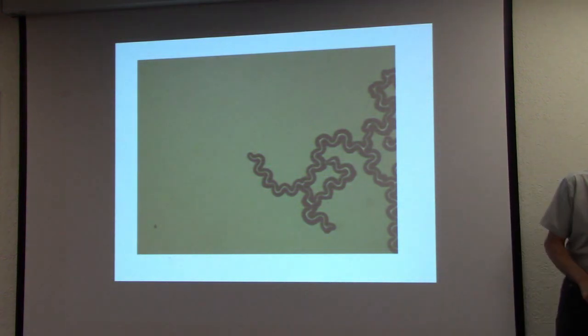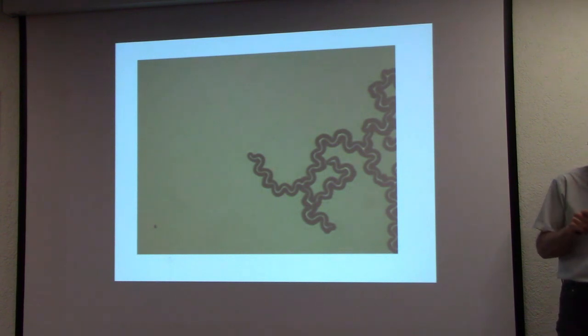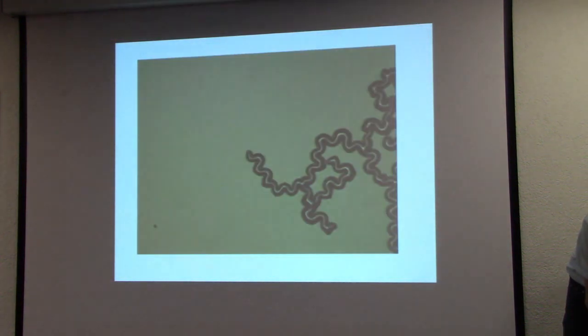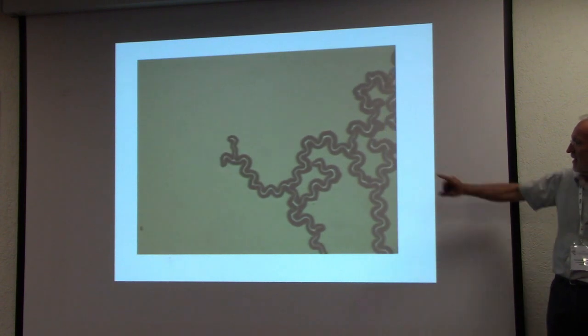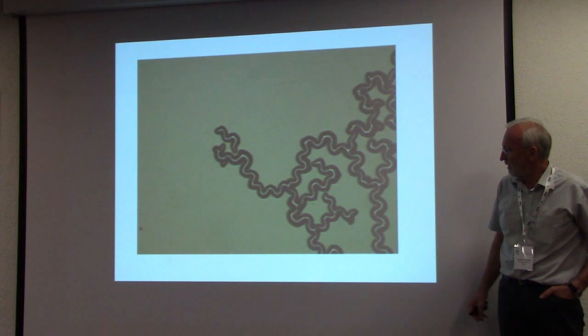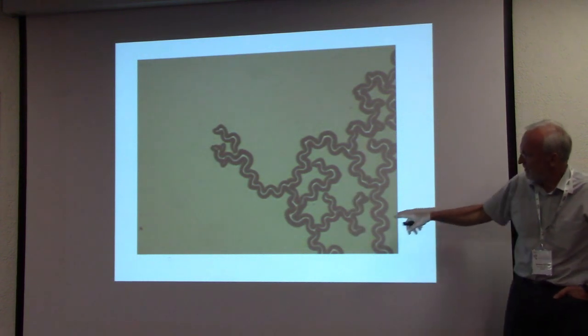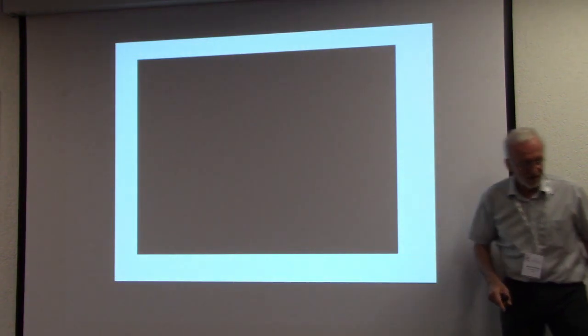The next thing what I want to show is these telephone cord formation, which are often the case when you have a film under compression loading, and the interface strength or the interface toughness is relatively weak. Yes. So when you have this stress, in this case, the film is under compression, and what happens is that here you get this formation of this telephone cord.